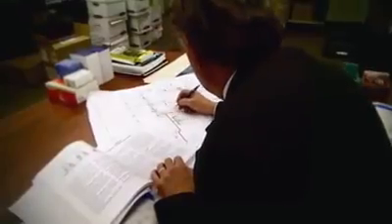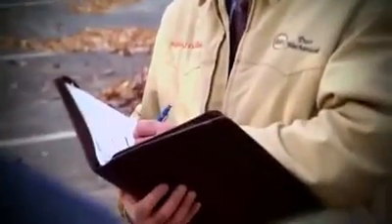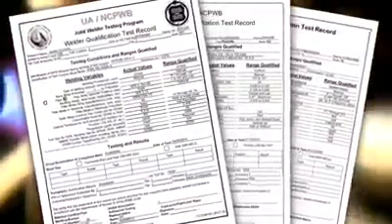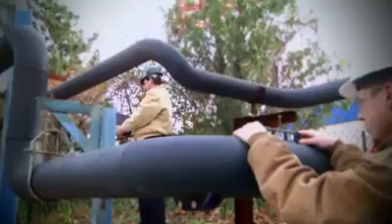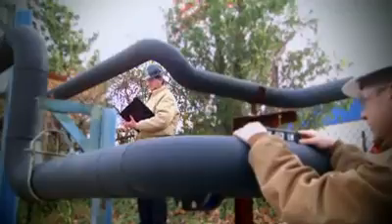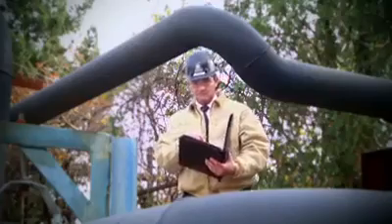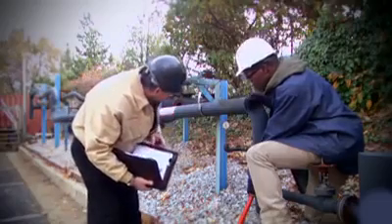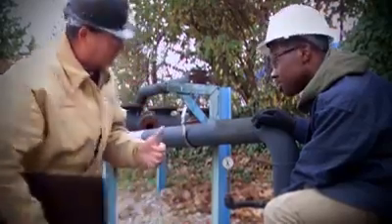While the engineer is responsible for material selection and design, the contractor is responsible for installing the piping following the specified B31 code section and the engineer's drawings and specifications. This includes being sure that the materials that the engineer specified are the materials that are installed, that the welders and brazers who will do the work have been properly qualified, and that those individuals are following properly written and qualified procedures when welding and brazing piping. The contractor is also responsible for examining the installed piping to be sure that it meets the requirements of the selected B31 code section, the drawings, and the specification. Finally, the contractor is responsible for pressure testing of the piping system, ensuring that it is leak-free.